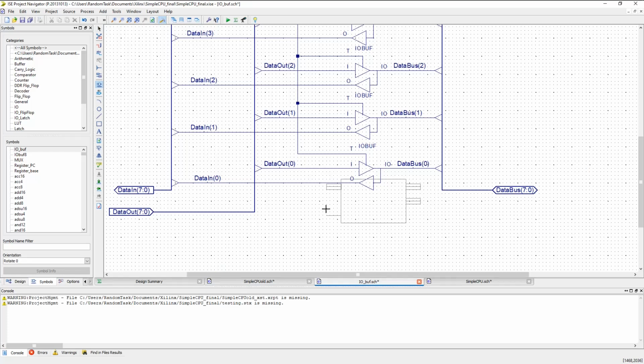It's necessary to use bus taps with this, which is one of the tools in the schematic capture toolbar, in order to make the buses work correctly, and you just have to name each wire with the bit position that tap represents. I won't go through the making of this block. By now you should have a feel for how to do it, and I'll leave it to you to finish. Leave a comment if you would like me to describe this further.